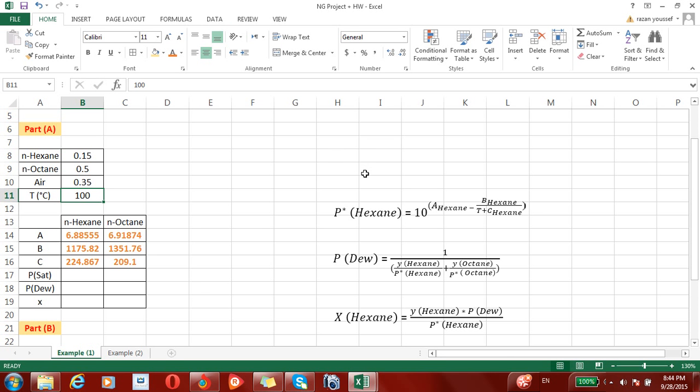And of course, if you are an engineer, you know that if we are going to calculate the saturated pressure, we always use Antoine's equation, which is a function of temperature and constants. I already found from my reference the constant values for A, B, C, which we are going to use in Antoine's equation. Of course, these values may differ. You might not get the same exact values, but they will not be that different across references.